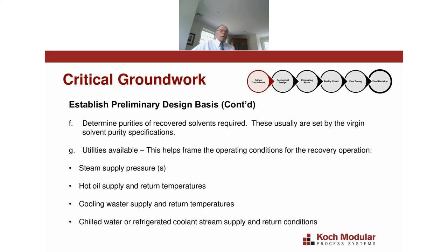For cooling, typically the cooling media is cooling tower water. So we'll need to know in the summertime what the maximum cooling tower supply temperature is and what the expected return temperature is. And sometimes clients will also need to supply chilled water or some type of refrigerated coolant. So we'll need to know what those supply and return conditions are as well.